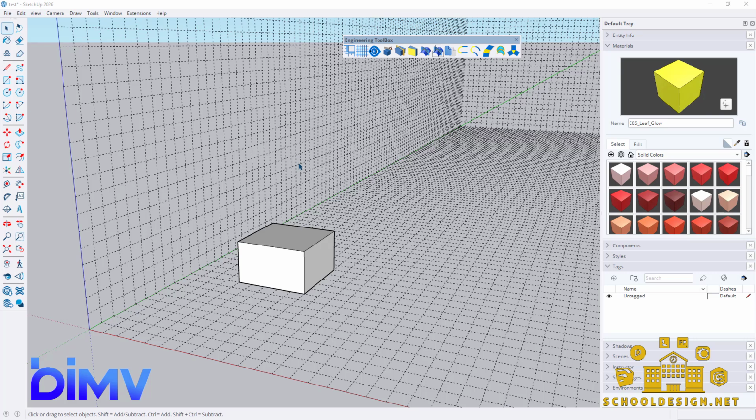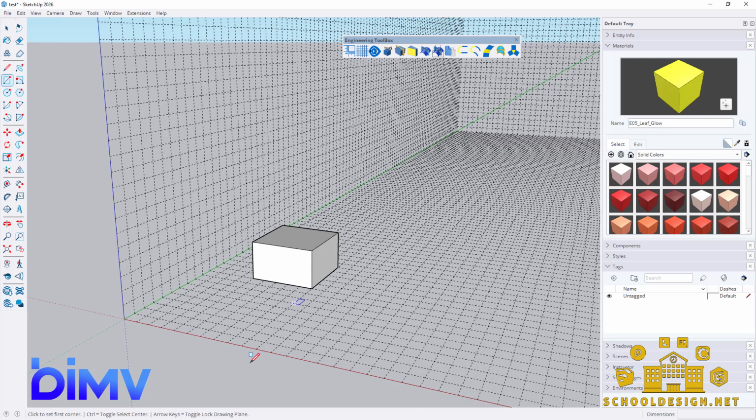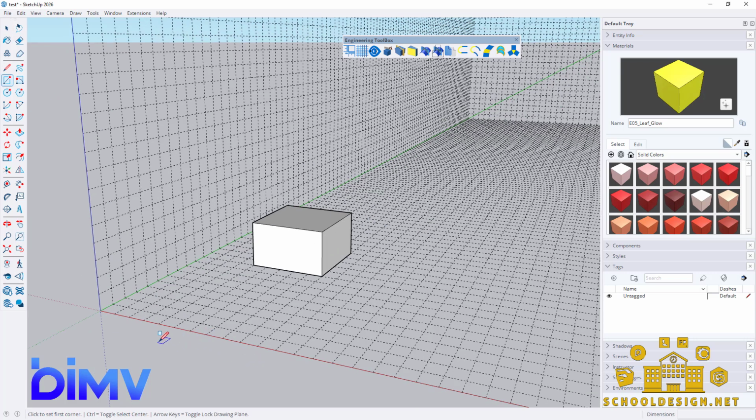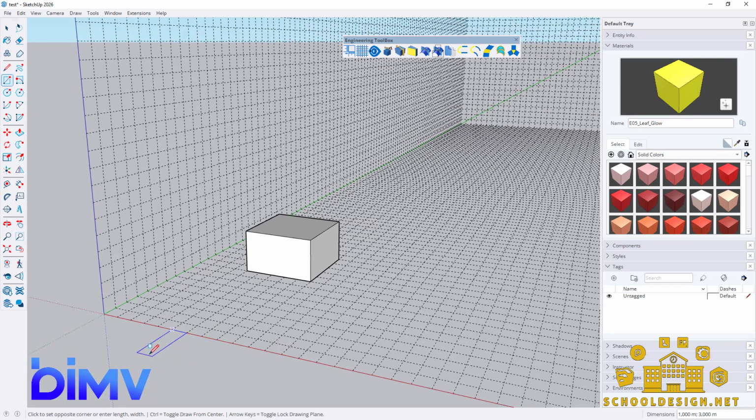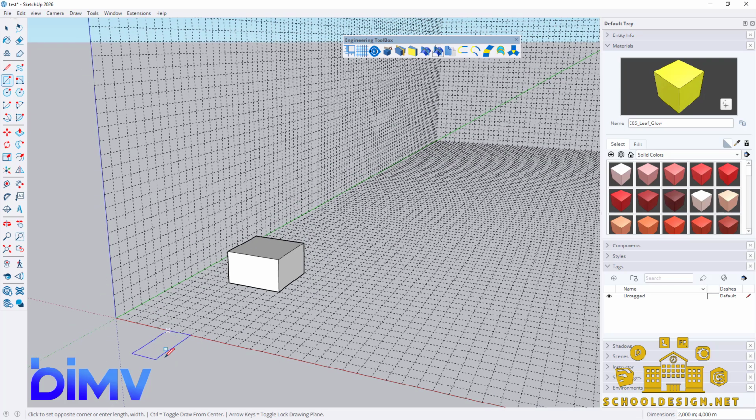Additionally, I mentioned that we also have the snapping set to 1 meter. So this means that if we want to draw our rectangle or some solid somewhere, you see that it now jumps much more easily every meter. We have the jump set to every meter, so it will be much easier for us to do this.